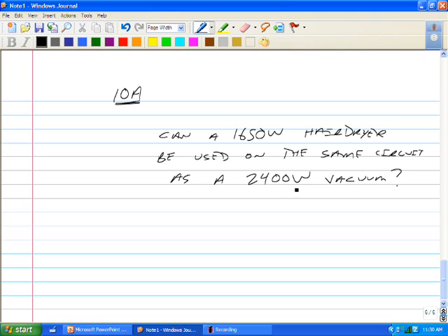Actually, the 2400 watts is not realistic. That's a little high. Let's make it 1800. If it's a 20 amp circuit.